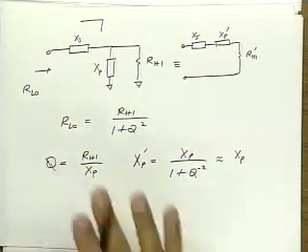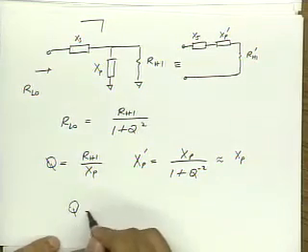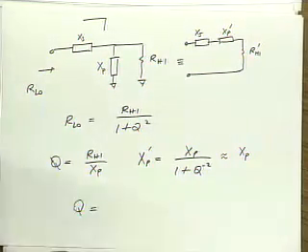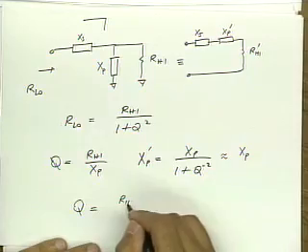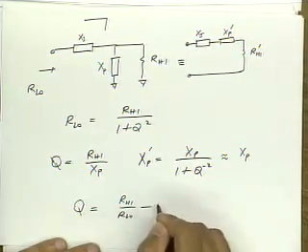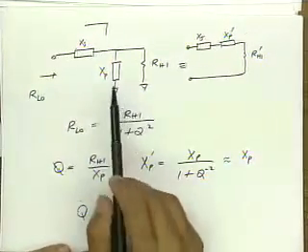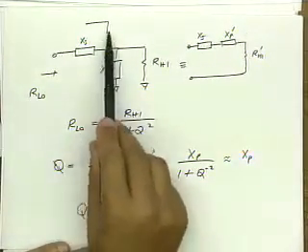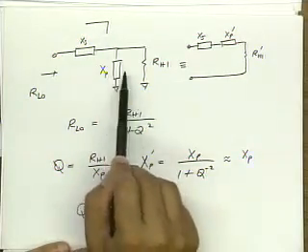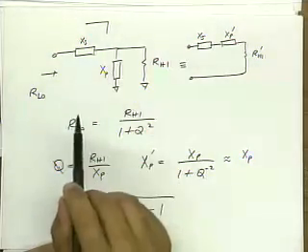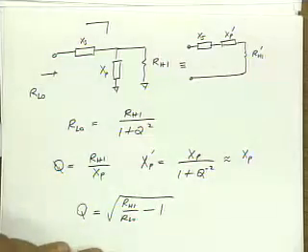So the only thing that changes in the design of high to low is, basically, if you just remember this equation, it's always valid. And the easy way to remember it is if I put my L network with this shunt element in parallel, it reduces the impedance. If I put it in series, it brings it up.